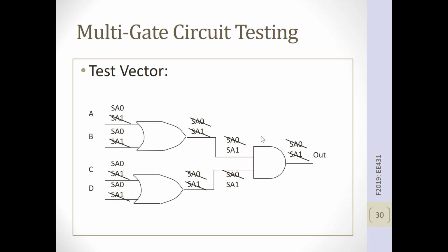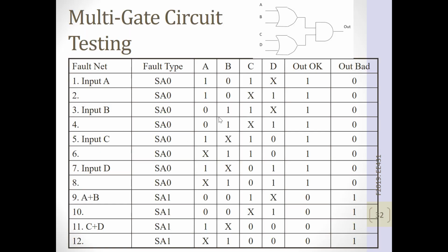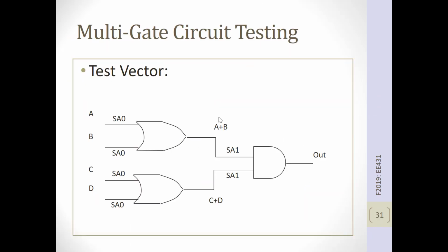And ask if that didn't make sense. So now you started out with 6 per gate, so 18, and now you're down to 2, 4, 6 tests total. So you reduce the number of tests by 2/3, and you're still exhaustively testing your circuit. Okay, so we ended up with these tests right here, these 6 tests to completely cover this circuit.